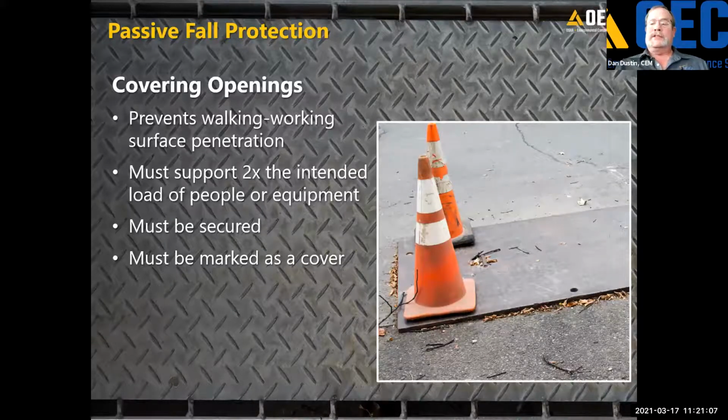When I look at standard construction, what we often find is 3/4 inch plywood covering these holes. And when I consider the potential traffic, keep in mind that a 20-foot scissors lift, 32 inches wide, weighs in at well over a ton, and 3/4 inch plywood will not be enough. So if I'm intending to drive equipment or materials over those openings, I have to have sufficient protection to keep from going through the cover.